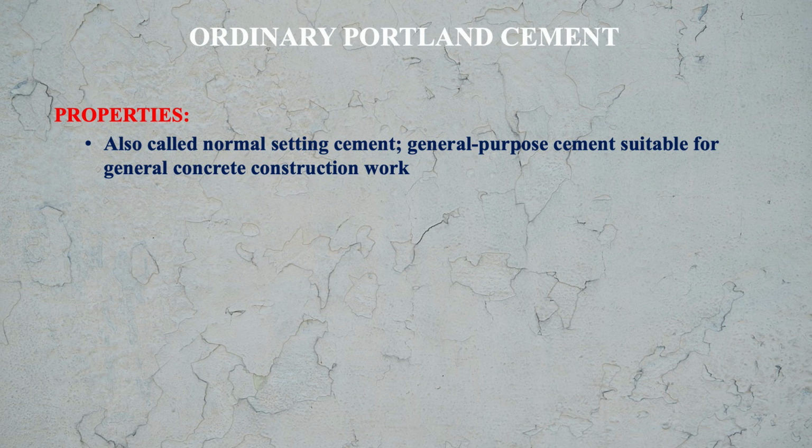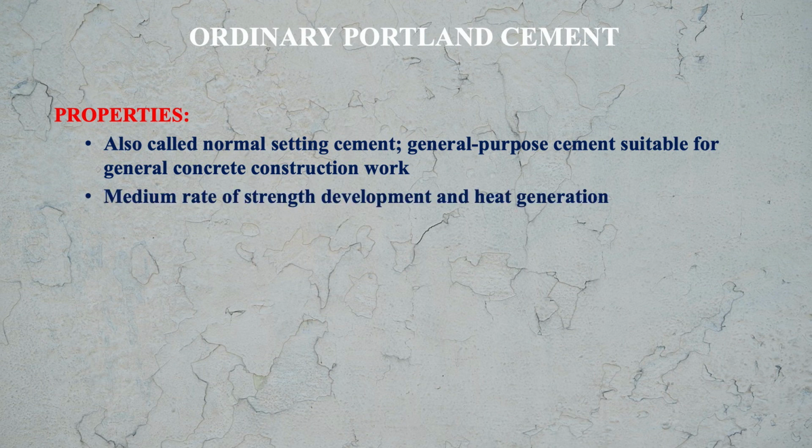This cement is characterized by a medium rate of strength development, and the heat of hydration is also medium. This cement has less resistance to chemical attack.